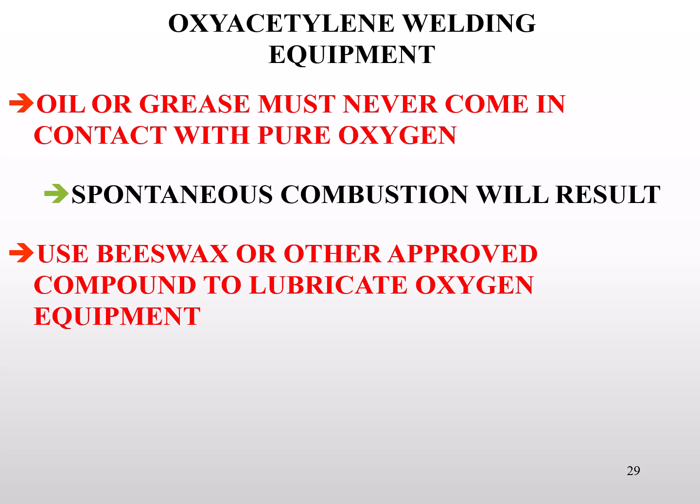When we are dealing with servicing or changing out oxygen equipment, you should never use anything petroleum-based to check for leaks or to lubricate threads. In the older days, beeswax was used. Now there are synthetic compounds we can use for leak checking, also for thread lubrication. Anything else that comes in contact could very easily spontaneously ignite, and it'll burn extremely hot and extremely rapid.